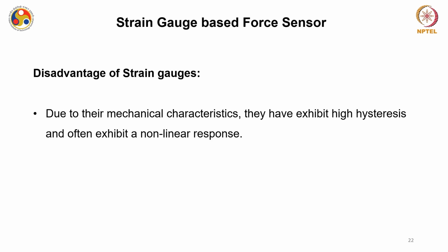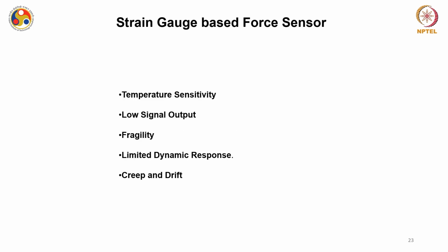If I summarize the disadvantages of strain gauges, there is temperature sensitivity, as I have just mentioned: due to variation in ambient conditions, particularly temperature, the strain gauge results vary at a large scale.